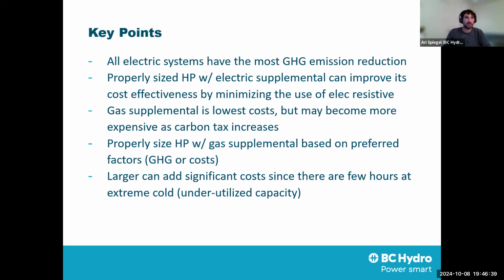I would say just cautioning that window replacements can be very expensive and have very long paybacks. So that number one thing that we encourage is reducing any leakage, like just sealing up the home so you don't have air infiltration. It's the number one energy benefit that you can do to your building envelope that isn't too costly and has great results.